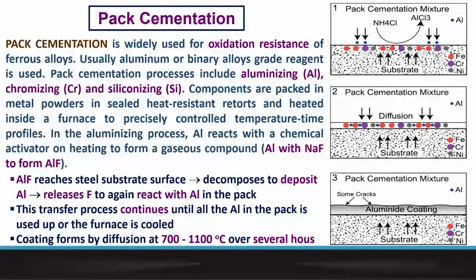The primary objective is to improve the oxidation resistance. As I already mentioned, these are the three magic elements: aluminum, chromium, and silicon. They are so-called magic elements because they very readily form oxides, and these oxides lie fairly low in the Ellingham diagram, or in other words, they are fairly stable and adherent oxides, and that's how they provide the protection.